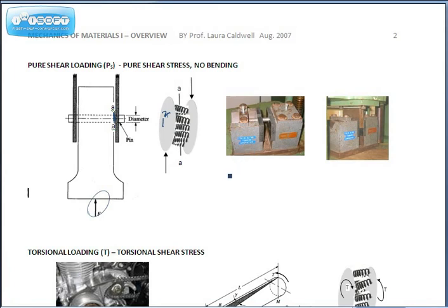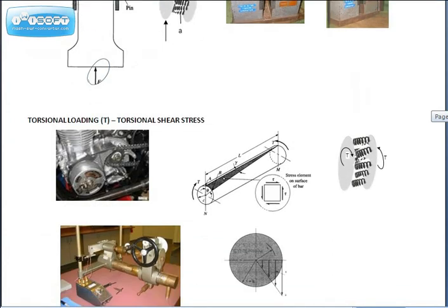It's a 1 square inch area, and we test it by putting it in a fixture. Here's our round sample, and we put a shear block on it. We have a machine that applies a force to it that tends to shear it, just like this picture shows. And we test it and make sure that when we put a pin in to hold some device in our fixture, it does not exceed what we got in our testing.